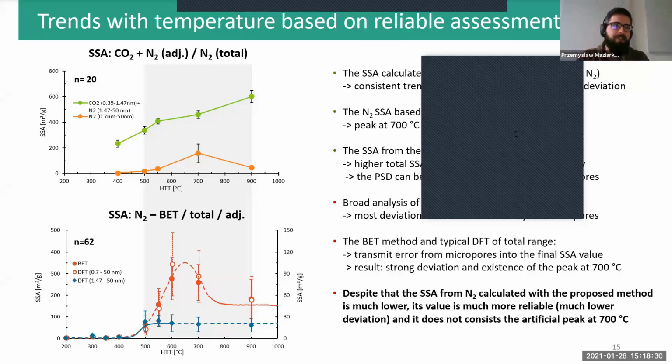Yeah, I've only mentioned that the degassing temperature can have a very strong influence on the assessment afterwards, on the outcome. Especially as Sigmund showed that for carbon dioxide it doesn't really change much, but for nitrogen it causes strong deviation in the result, for the same production temperature but degassing with a different degassing temperature.